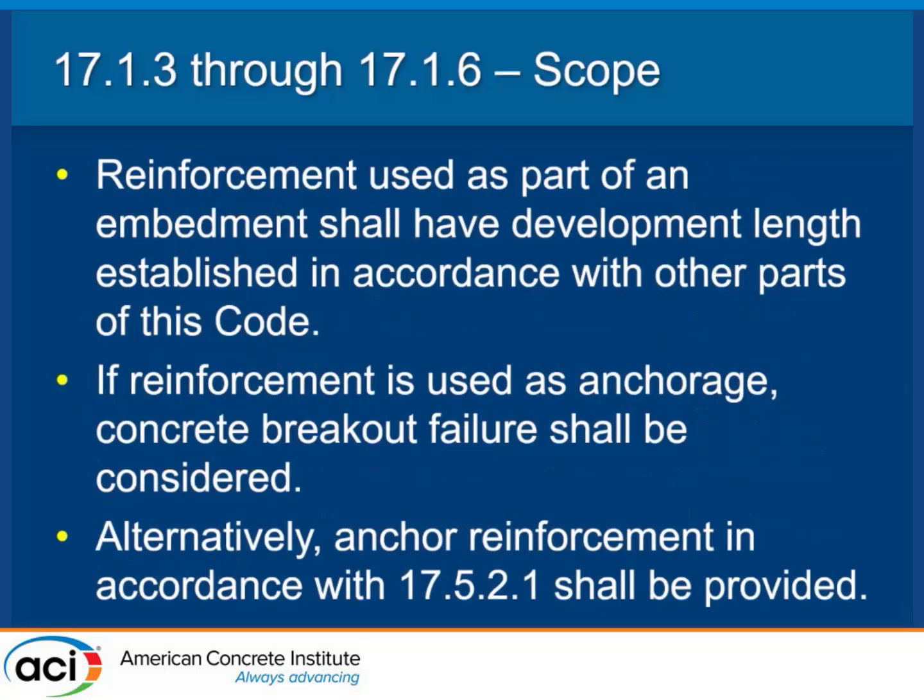Reinforcement used as part of an embedment shall develop the length established. So you can use reinforcement as anchorage. That's okay. Its effective depth, so to speak, or hef we talked about earlier, is the development length equations that you use in 318. So if you want to use steel reinforcement, you can use it.